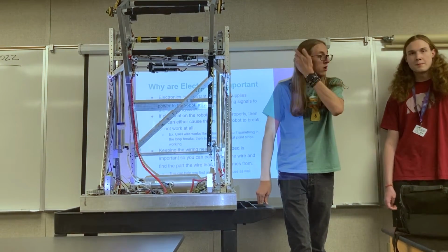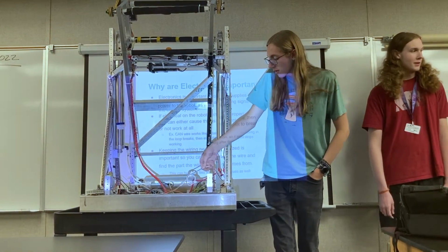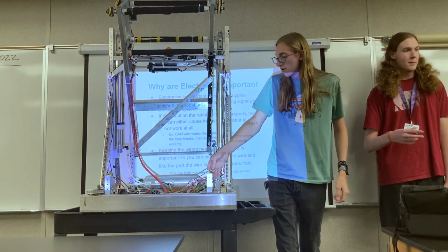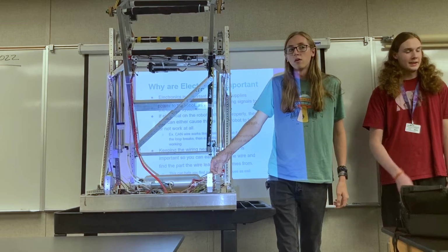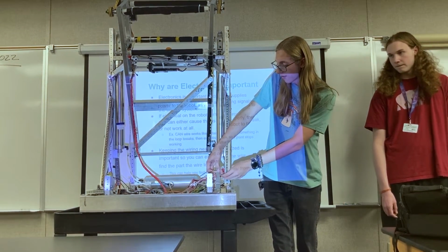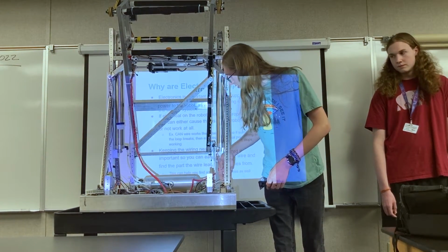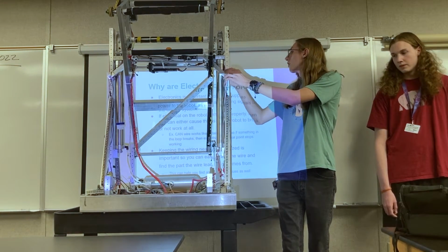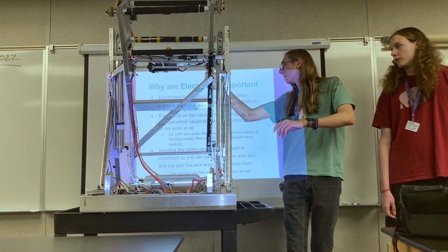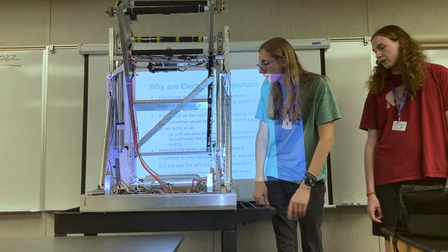As opposed to the other method, which is PWM, where each device is directly connected to the RoboRio, and then it just sends the signal to that channel instead of having to go through a bunch of things which I might not need to use before sending it to a component which needs the signal. Those are these white, black, and red wires right here. We use them for some of our motors, not all of them. I believe this one up there is PWM. Our solenoids, I believe, are PWM. I think all the motors currently are using PWM.